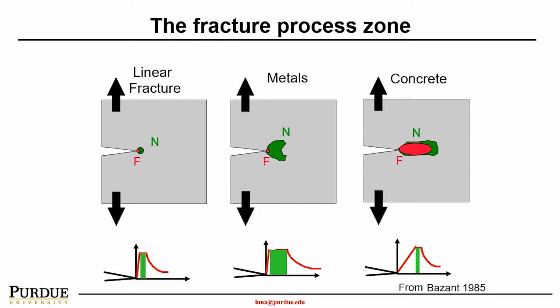So linear elastic fracture mechanics works really well for brittle materials or ductile materials such as steel. However, it isn't very relevant to quasi-brittle materials such as concrete. For instance, in linear elastic fracture mechanics, you consider there is an existing crack, and then there is a non-cracked surface.